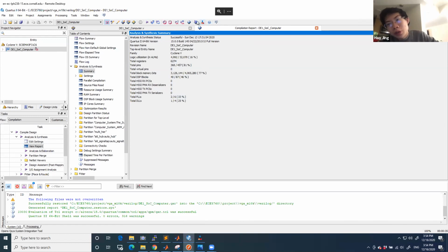After we used the M10K blocks, the logic utilization reduced to 60%. Were you running out of registers? Do you have things stored in registers previously? Yeah, because as Professor Bruce said earlier, we have really complex indexing for the arrays, which makes a lot of lookup tables to implement. Changing to M10K blocks requires timing changes, so we just rewrote the state machine. That's a big refactor, and it's a pain in the neck.